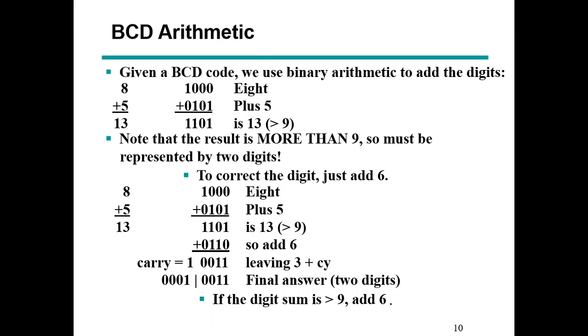Okay, so we looked at it in our last lecture. There was a slide where we talked about the difference between conversion and coding, and we looked at this example. I guess it was 13 or something. So when you convert 13 into binary, this is what you get. But when you code 13 as a BCD, in BCD, this is what you get. The 4-bit BCD code for 1 and the 4-bit BCD code for 3. So this is binary conversion and this is BCD code.